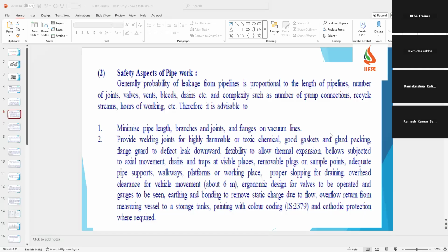They go almost to the bottom of the reactor, because we could charge the material from the top also, but we have dip legs till the bottom of the reactor to avoid generation of static electricity by giving the material at the bottom.